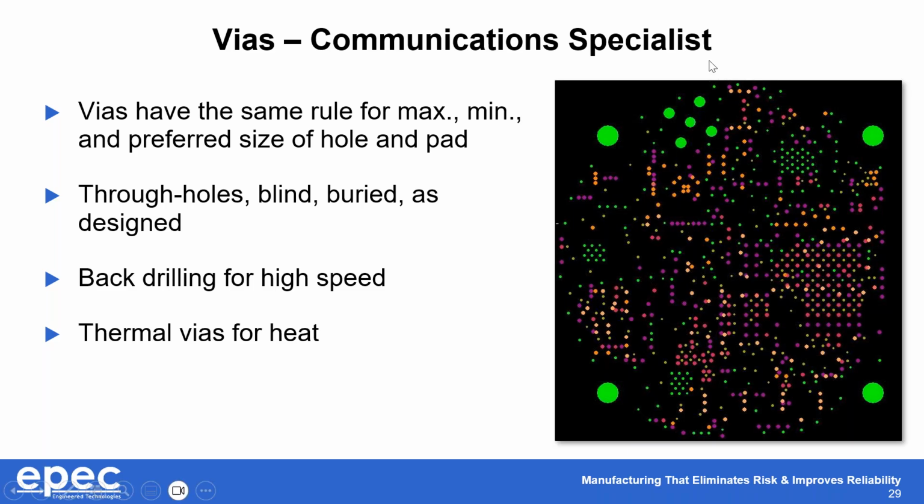There's no blind or buried that are green. Everything else, the peach and the purple and the red and any other color you can see in there, those are all buried or blind. There are no back drills in this picture, but we also do back drilling to remove the plating from one side or the other. We also do vias for removing heat away from components. There aren't any on this board, this picture, but it is possible to add vias to layers to help disperse heat from components.